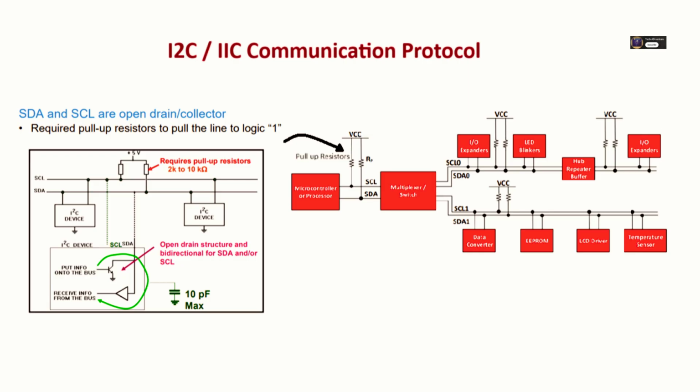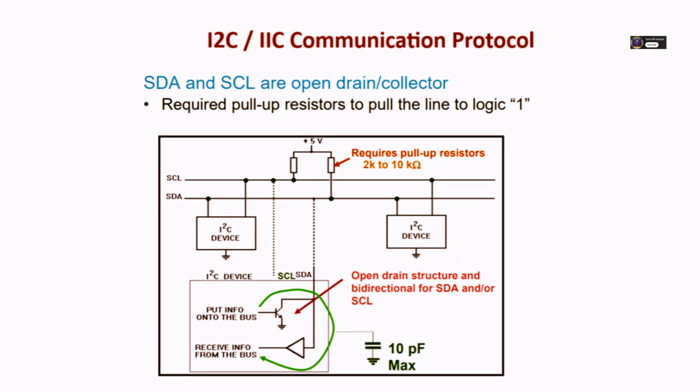Sure. Imagine a regular light switch. It can actively turn the light on by supplying power, or turn it off by cutting power. Push-pull, right? Yeah. An open drain output is more like a special switch that can only do two things. It can turn the light off by pulling the wire straight down to ground, or it can simply let go of the wire, essentially disconnecting itself internally, letting something else control the state. It cannot actively push the wire high. It can't force the light on itself.